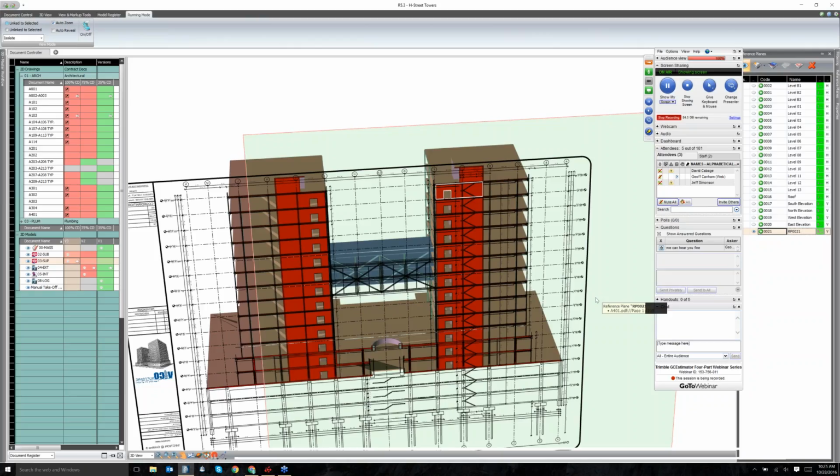So when they're drawing in Revit, these 2D drawings are actually coming from the models. What can be kind of a hurdle sometimes is getting quality models for construction from architects. But with a little QA/QC, you can see that most of these models are actually really good and can be used. Not for everything. 2D is still going to be part of our workflow, but what the models do is give us quick understanding and also quick quantities that we can verify.